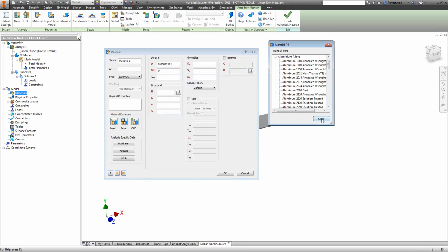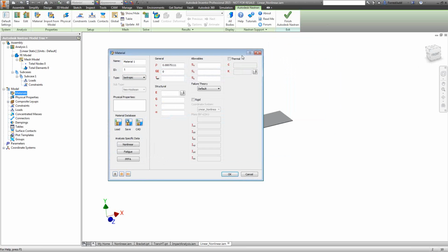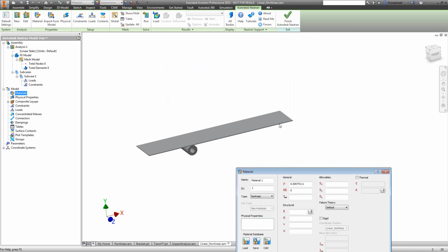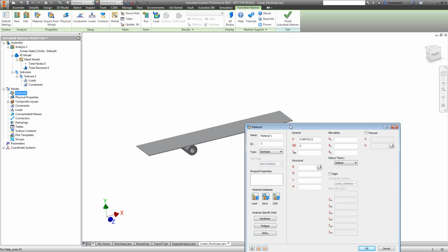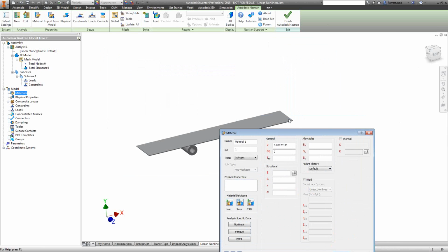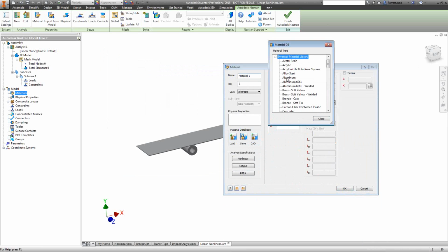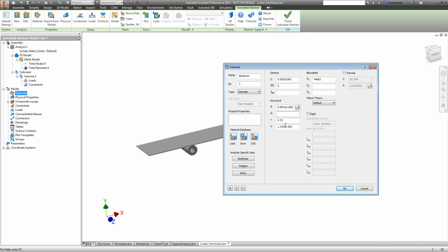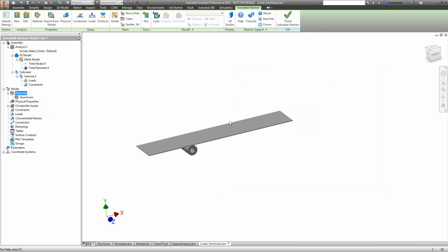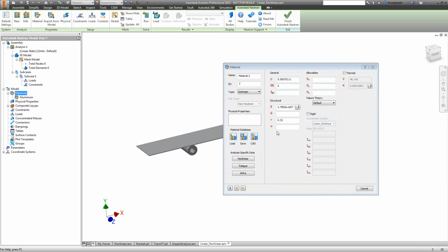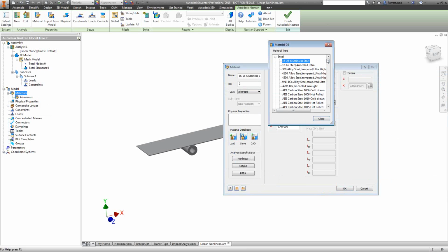So I know in this case what I'm looking for, we're going to simulate this plate and how it might rest against this stop as we apply a load on the far end here, and it'll be pinned at the back. So we're expecting a fairly large deformation here, and this is where we might want to investigate linear versus nonlinear. So I'll start with the linear approach. And we have an aluminum material here. We're going to have a steel material as well.